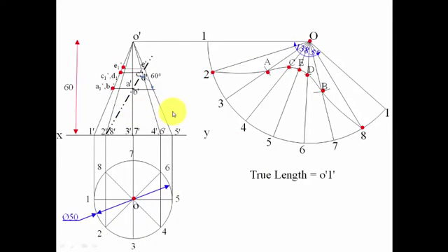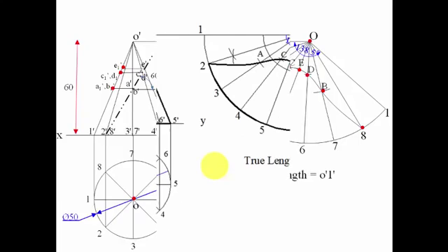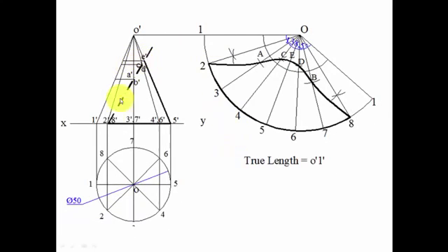And now finally I need to tell you guys which portion is to be darkened and which is to be left as it is. So initially all the drawing that we have made can be carried out with the help of a 3H pencil, and finally the portion which is to be darkened should look something like this, and it has to be carried out with the help of an H pencil. That's it. So this portion you see over here below the cutting plane has to be darkened. So this is the portion which has to be darkened.